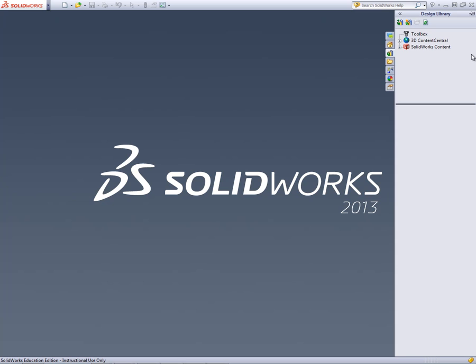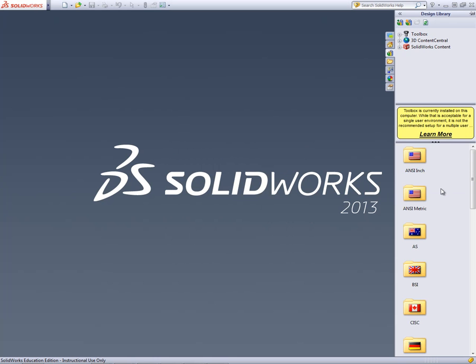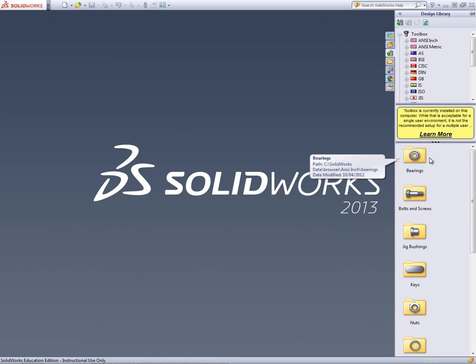We'll left click once, then we'll double click on the toolbox icon, and an error will show up and say the toolbox is not added, add now. So we'll left click on add in now, and it's simply just going to load this toolbox. And what we'll do is pull some existing parts out of the toolbox. So we'll double click on ANSI inch, and we'll start with a bolt. That's more of a simple part that we can import from the design library.